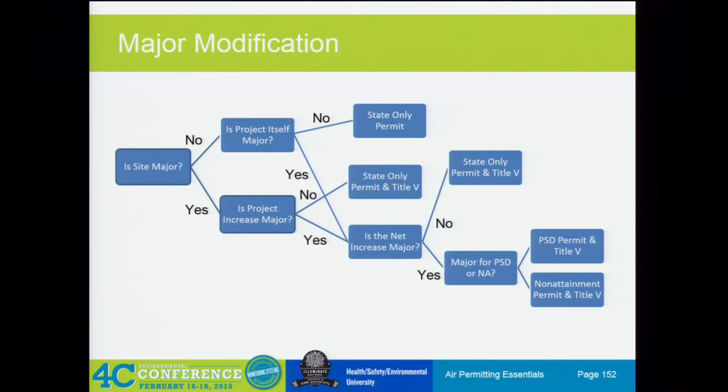If you put a permit condition saying I'm only going to operate this boiler for 6 months out of each year, you wouldn't have to necessarily authorize the emissions for a full year. You can authorize it for the 6 months, get it put into an NSR permit through your state, and that becomes a federally enforceable limit. And so instead of 100 tons, that boiler is operating at 50 tons, and that's what your PTE is.